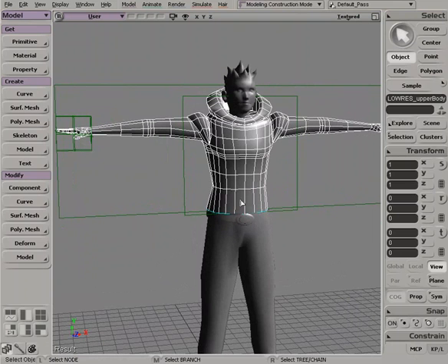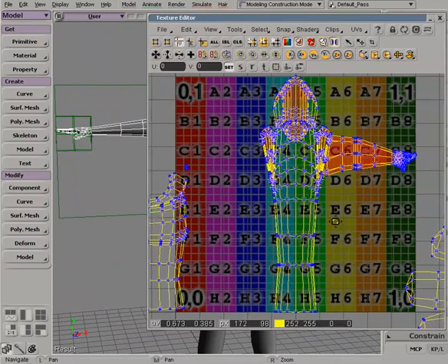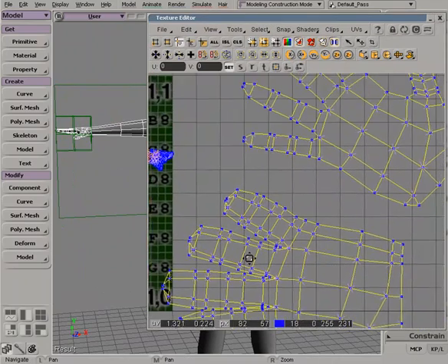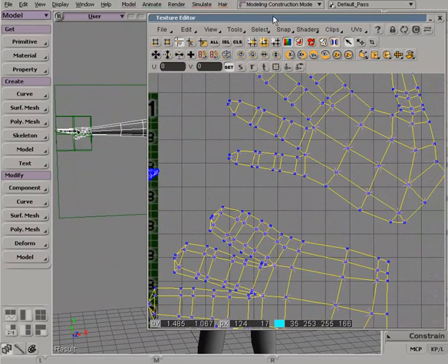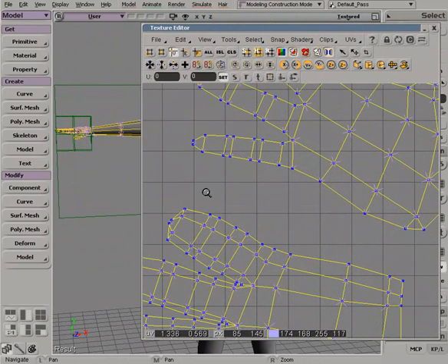Alright, so opening this model back up, I'm going to select the chest and Alt-7 to open up my text editor once again. One thing that I do want to show you before we wrap up with the process of working with UVs in XSI is how we can actually heal UVs. So the Heal UVs tool can actually be found right here. It's this little plus icon. So the process of healing UVs is actually a pretty straightforward one.